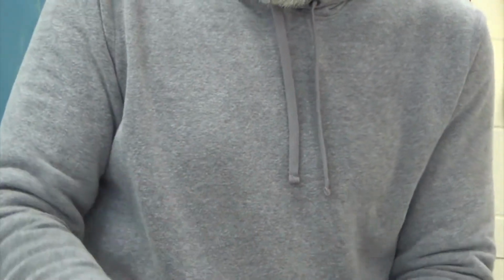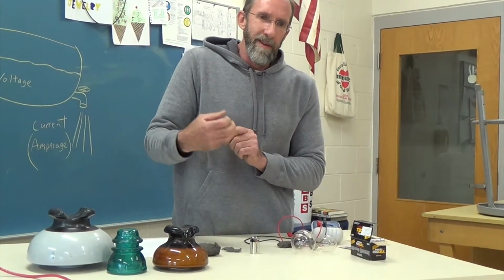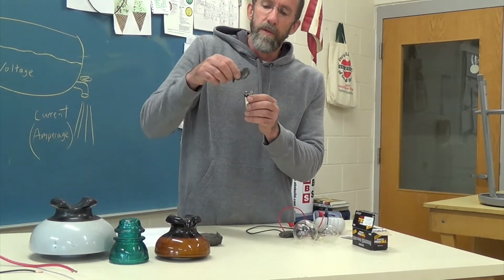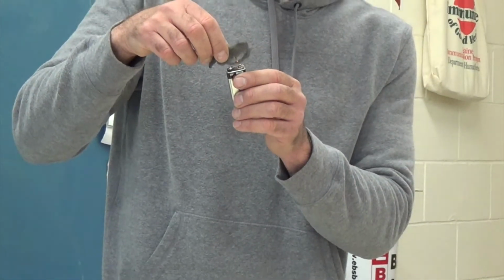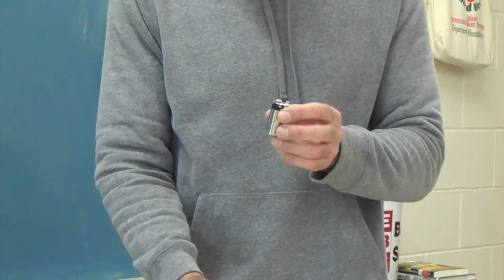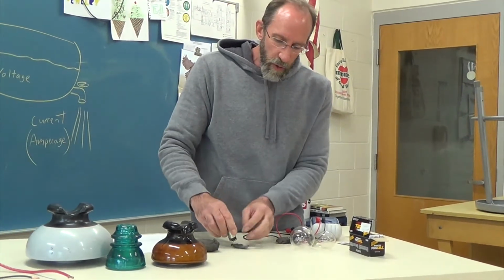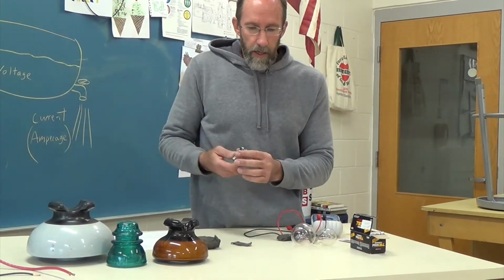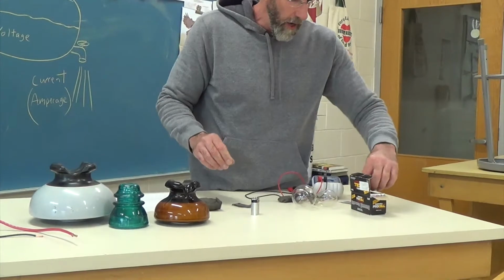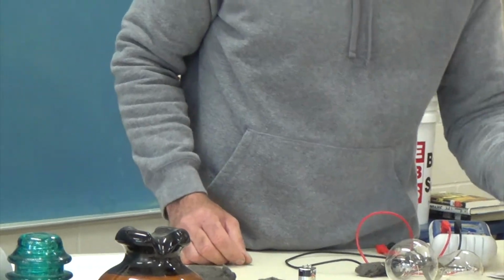So it's kind of like if you look at your toaster in your kitchen, you see those glowing wires, you're forcing electricity through a conductor that's not really a good conductor, and so it heats up just like that. The reason this one heated up is because the wires are so small, the electricity's just having a hard time getting through there, creating a lot of resistance. That's why you have to be careful with 9 volts. Since the two connections are close to each other, you can get that same kind of short circuit in your pocket with change, or putting them in a metal container, or with other batteries and things like that. You got to be careful with those. Round batteries, you don't have to worry as much because the ends are so far apart. They're not going to end up shorting each other.